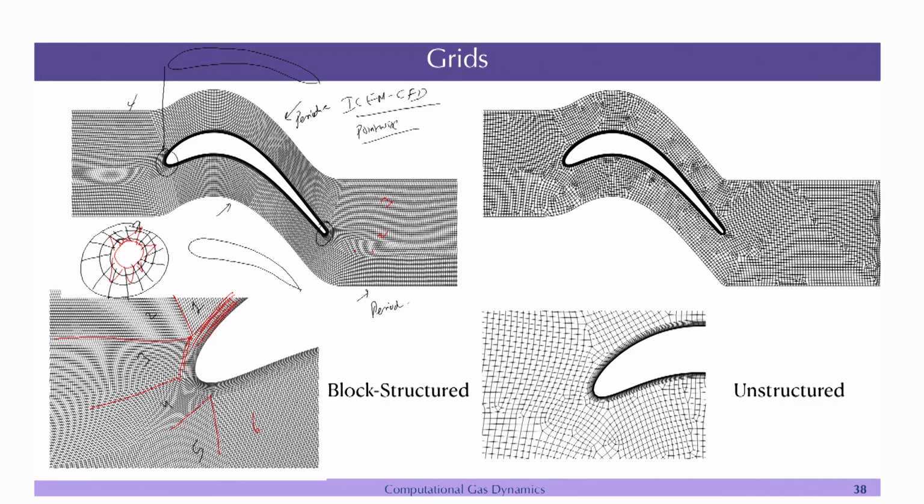So, making a block structured grid is time consuming, but it gives you more accuracy than an unstructured grid. If you look at the unstructured grid on the same geometry that we have, I am showing you a coarser version just to make a point of how the grids can be made. Here also you can see that the elements are in all directions. There are some elements which are quad, there are some elements which are tri. Let me show you the zoomed version here.